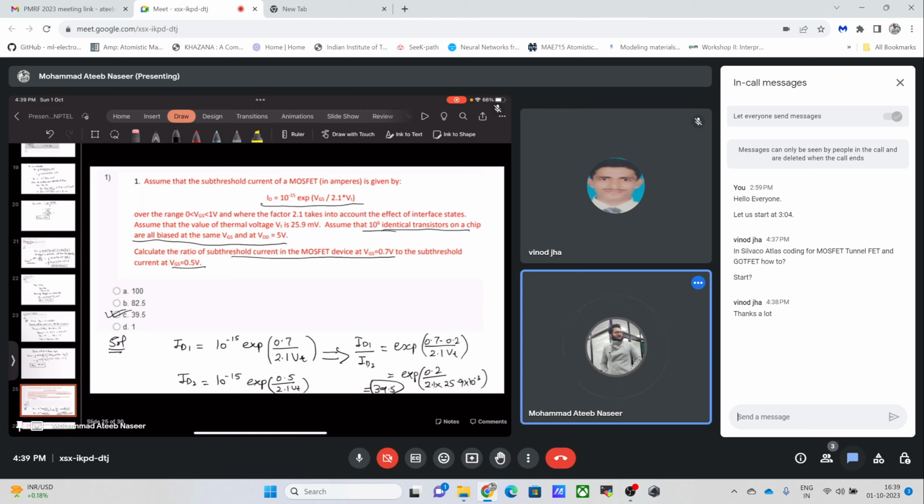You would say that this kind of trapping I have seen, this is this kind of trapping mechanism that should occur, or this kind of tunneling mechanism that could occur at this particular channel length or at this particular bias. So you would include that particular tunneling model, or that particular trapping model. So it goes like that. You have to go through the manual and keep the device physics of these structures in mind, and as a result you will be able to solve, I guess, every problem that you face in Silvaco Atlas or anything.